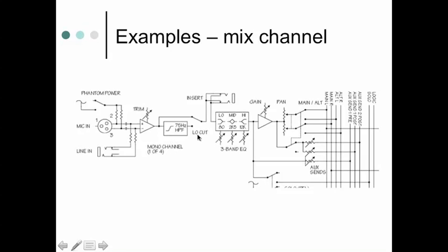And then here is a filter block where you can filter the signal in terms of frequencies, like what we were talking about, taking out high frequencies. This actually is a high-pass filter, so it says HPF, which passes only high frequencies and rolls off some of the low frequencies. So if you have a little rumble in your signal, you can insert that, and it'll take the rumble away from it. Because if you're on a live stage, sometimes there's rumble from the sound system and so forth.